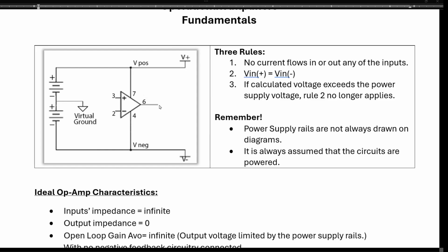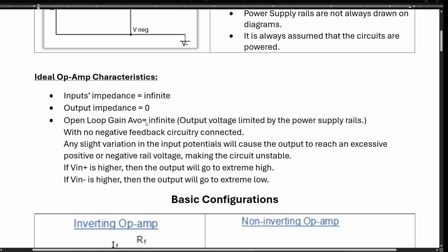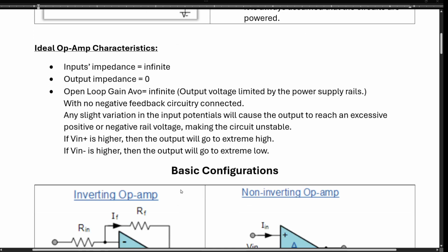So for the LM741, the higher limit of the voltage swing is going to be about 14 volts with the power supply at 15, about 1 volt less either way. That's as far as I remember from the data sheets of the LM741. There are some other ones, and you have to find that out. That's why we have the data sheet, to tell us what the maximum voltage swing is. So this basically here is what I just explained. You can read that once you download it.